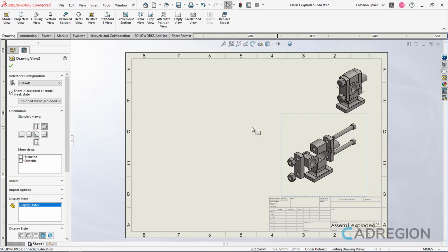As I mentioned before, in assemblies, we usually do not place orthographic views of the entire assembly. However, you can place orthographic views of any assembly and also add dimensions if you want, in the same way you would for a part. Now to present the assembly correctly, I have to insert the necessary orthographic views of each part and also add dimensions to them.